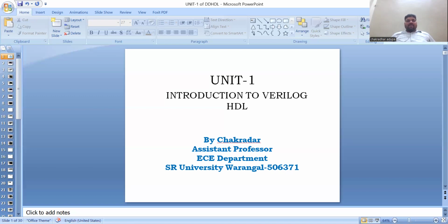Reg value: reg is a keyword, value is an identifier. And input clk: input is a keyword, here clk is an identifier. Reg value means value is an identifier, reg means it's a keyword. Input clk, input is a keyword and clk is an identifier. The double slash in this statement indicates that it's a comment. By writing a double slash beside an instruction in Verilog, we can mention any comment related to the instruction or the meaning of the statements.